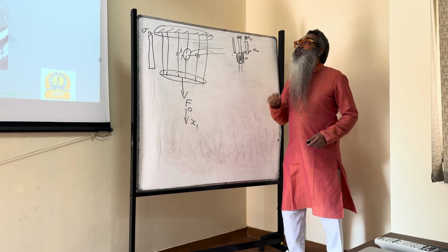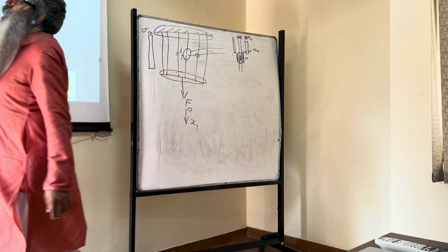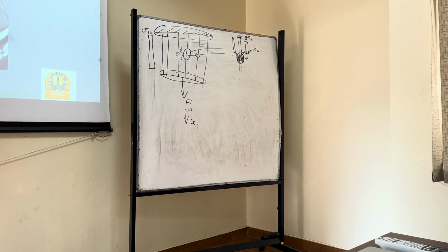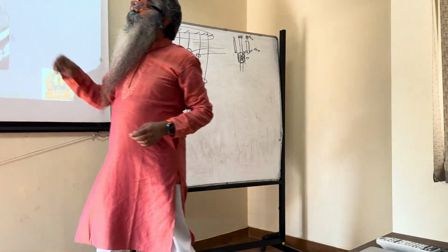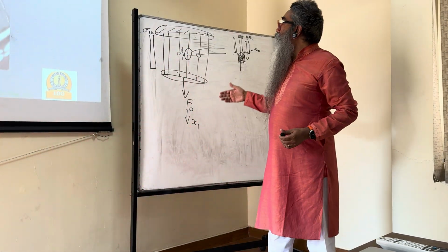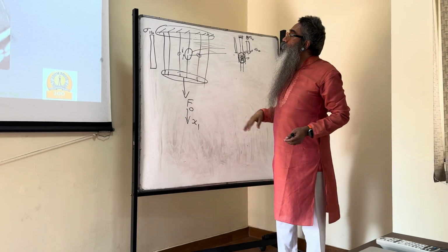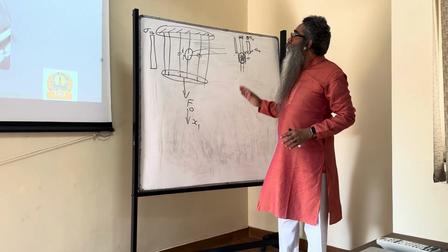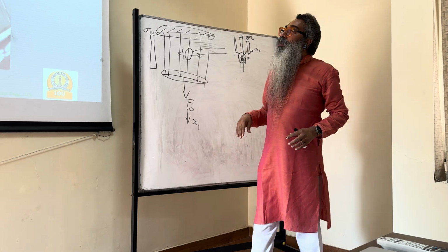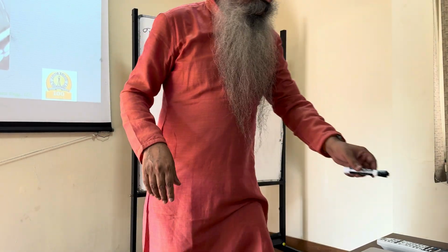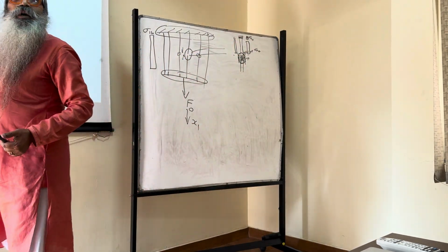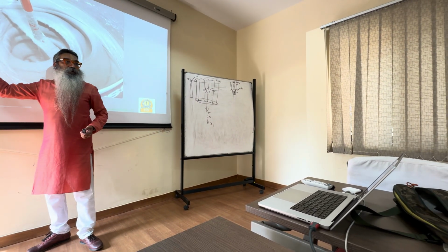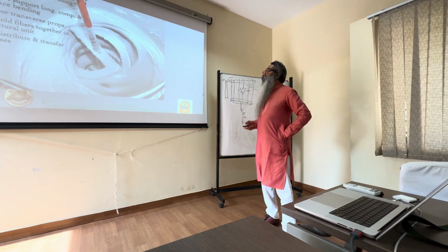So now you see the importance and relevance of this particular functionality of the matrix that we're talking about, to distribute and transfer the stresses, because without that the overall performance of the bunch of fibers will be much more inferior. The stress transfer will not take place between broken fibers. Is this clear? Because this is a very important topic in terms of stress transfers. Though we're not going into it quantitatively, qualitatively understanding this is important.